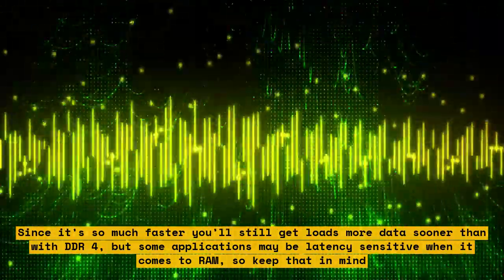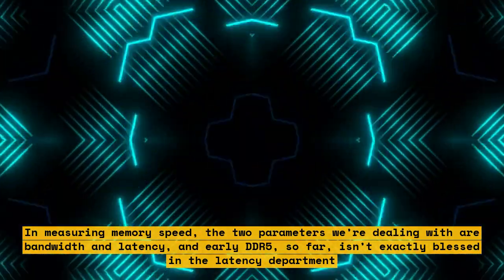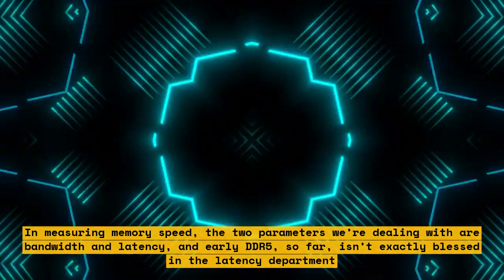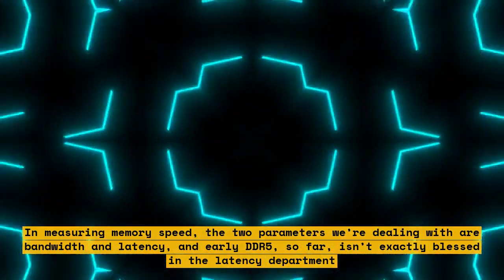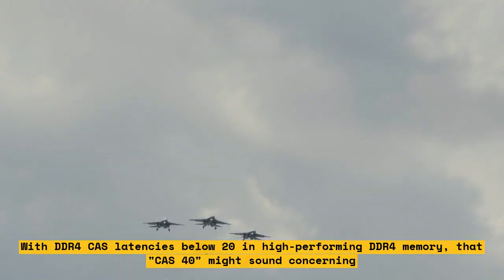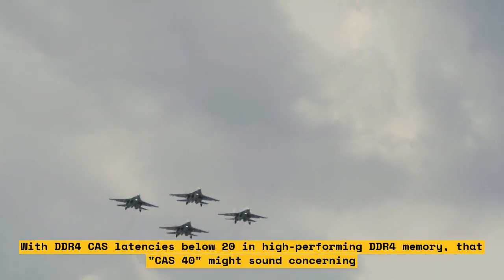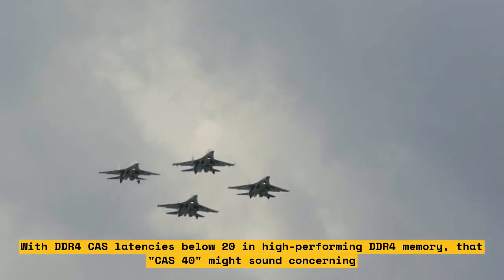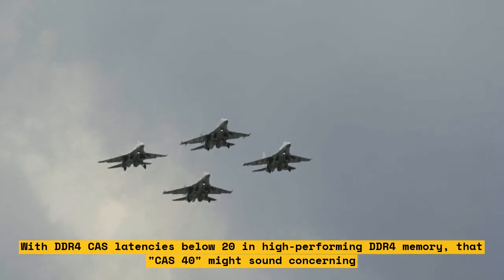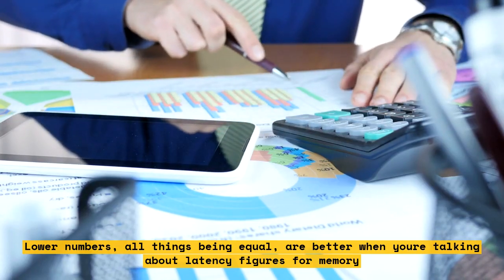In measuring memory speed, the two parameters we're dealing with are bandwidth and latency, and early DDR5, so far, isn't exactly blessed in the latency department. With DDR4 CAS latencies below 20 in high-performing DDR4 memory, that CAS 40 might sound concerning. Lower numbers, all things being equal, are better when you're talking about latency figures for memory.